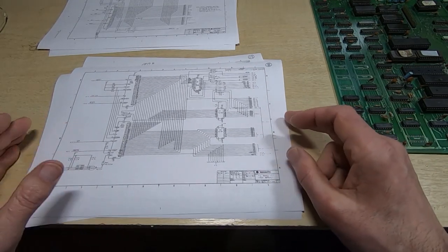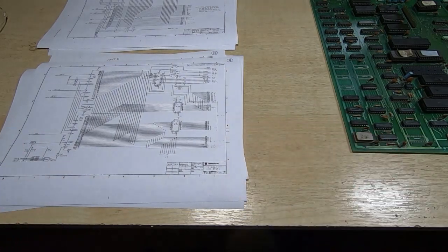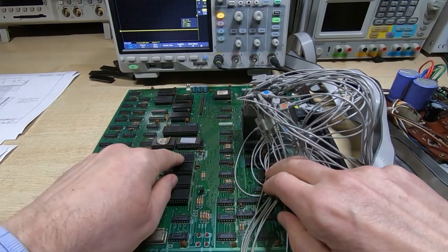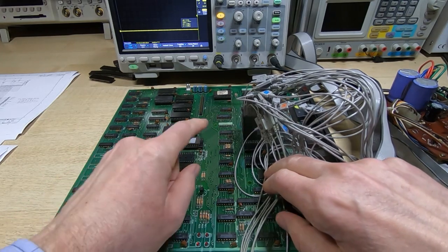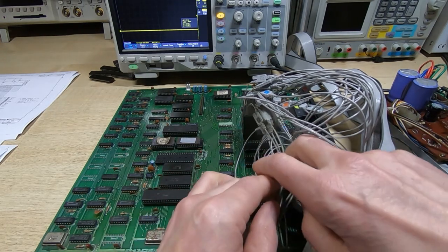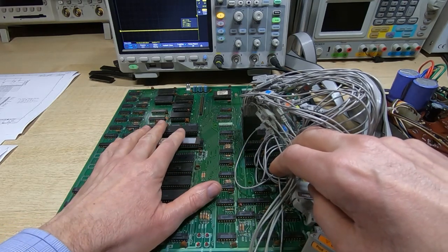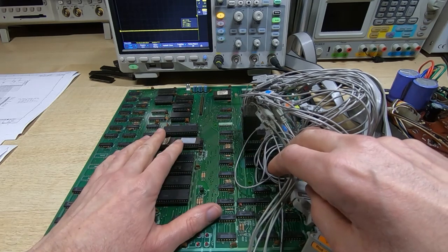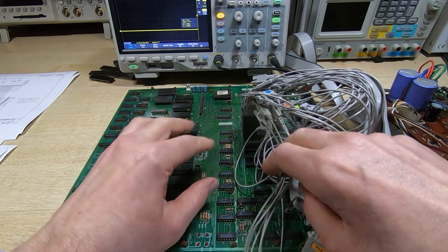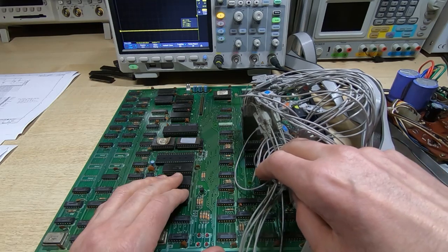So we'll go back to the PC and I'll explain how I've tried to minimize the possible interactions. What I've done to try and get the Z80 to go into its self-test is I've removed the 6502. That allows the reset to be released for the Z80, so it comes out of reset and should start to run. I've also unplugged the two SIOs, so there's no chance of the 6502 system doing anything. It probably wouldn't anyway, because with the 6502 removed, there's no way to generate serial data. I didn't want just noise and possible rogue data finding its way into the Z80 system.